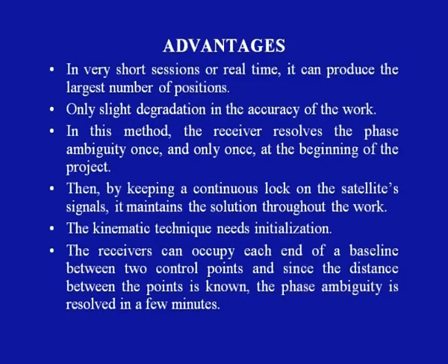The advantages of kinematic surveying is that in very short sessions or real time, it can produce the largest number of positions. Only slight degradation in the accuracy of the work occurs. In this method, the receiver resolves the phase ambiguity once and only once at the beginning of the project. Then, by keeping a continuous lock on the satellite signal, it maintains its solution throughout the work.